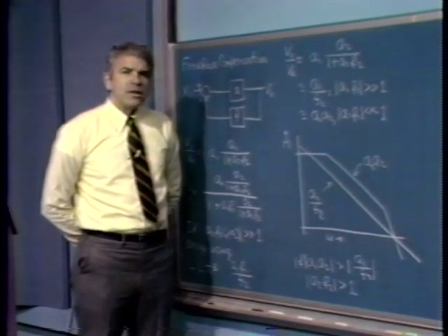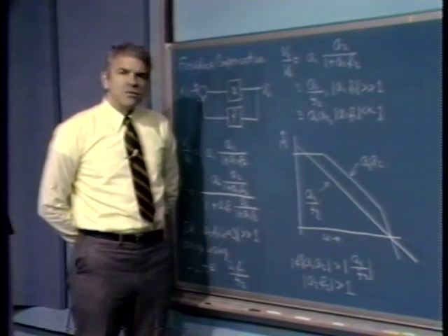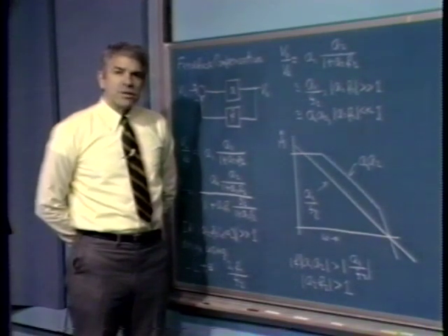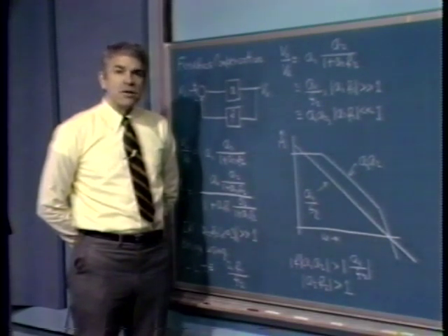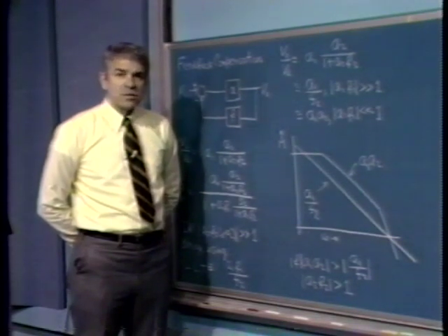Another possibility that you may be familiar with is the use of a tachometer in a servomechanism. What one does with a tachometer is measure the output velocity of the system and feed that back in a way that forms a minor loop. The tachometer, of course, introduces a differentiation between output position and its signal.